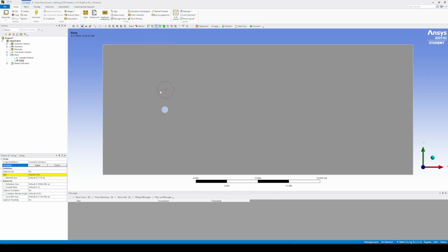So we're going to press edge up there, select this, click apply. The only thing here is that we're going to change type to number of divisions. Perfect. And we found that 200 number of divisions worked well with our mesh. So we're going to do that. Curvature, change soft to hard. Perfect.